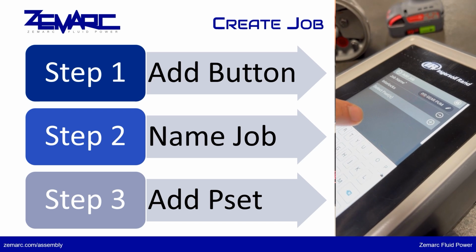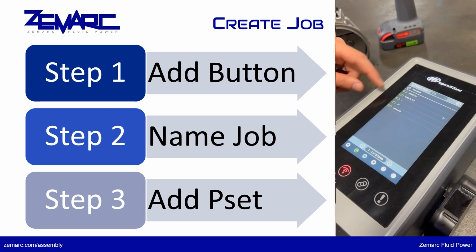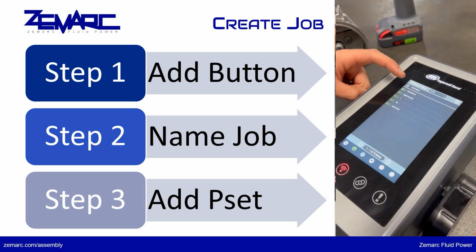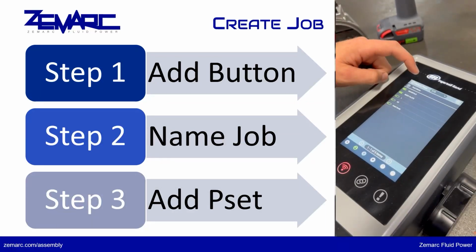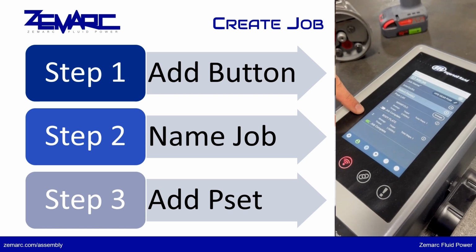Since we've also implemented batch counting, 4 cycles of each PSET, the tool will automatically sequence from one PSET to the next once all 4 bolts of each have been completed. But if there's a problem with torque or fastener length or anything outside of the parameters we've set, the technician will not be able to advance without taking predetermined steps to correct the error.